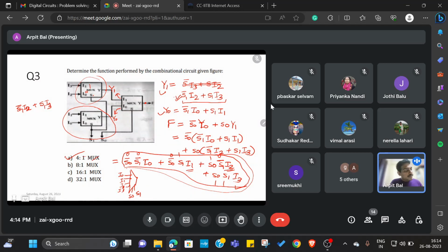So we tried to figure out the intermediate node equations, we tried to solve those, and we tried to solve what is going to be the output. My suggestion is, if you are well practiced with these equations, you can figure out what this entire black box represents. You don't need to go through all the procedure. You can directly say that this is a 4:1 mux.